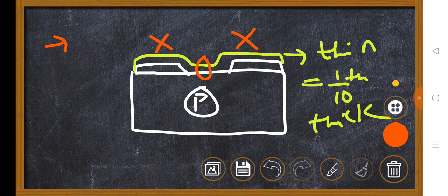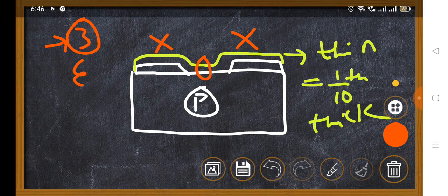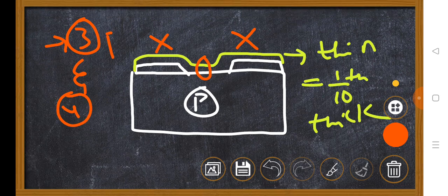Absolutely. I have to repeat step number 3 and step number 4, that means the photolithography and etching process. Is it clear? In the same manner as we did in the previous class steps. Then after that, I would like to maintain this gate oxide in this place. I would like to remove this gate oxide here. I hope you are clear.